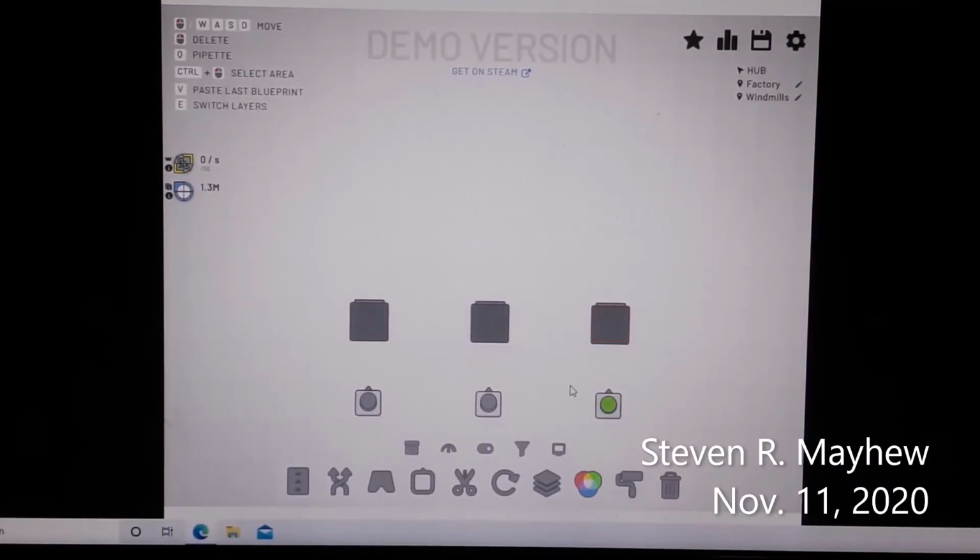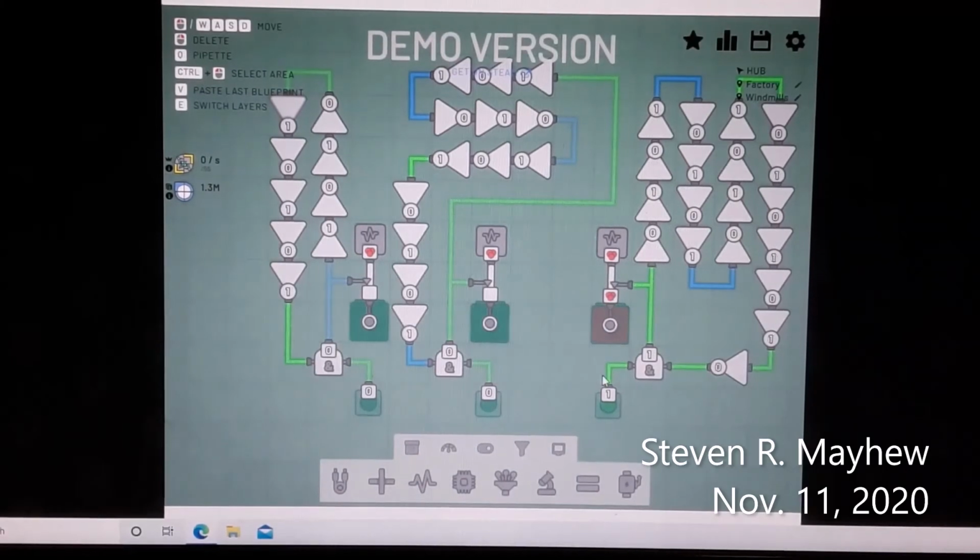Have you ever made a flashing light in this game? How is that possible? Well, there's a simple solution to that. Make a series of inverters, and you'll always want to use an odd number of inverters. And as you can see, it takes time for the signals to travel through all of the inverters before reaching the AND gate, in which the switch controls the other input of the AND gate. And that's what causes the light to flash on and off.